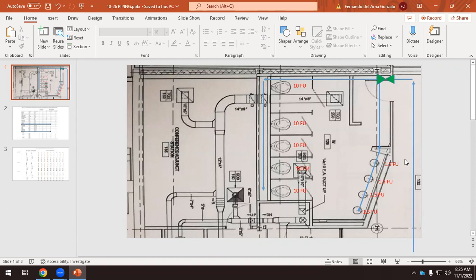So at the entrance of every restroom, we have this. If you have decided that this pipe enters the restroom here, the shut-off valve will be here, and it has to be accessible. Those shut-off valves, if you take a look at it, should be accessible. Probably, if you don't find it, it's not in the false ceiling because that would be too difficult. It's probably in the janitor's room in this area. It's very easy to understand where this is. If there's an issue, you call maintenance, and they shut it off immediately. They don't have to remove the tiles of the false ceiling to find this. So it should be accessible.